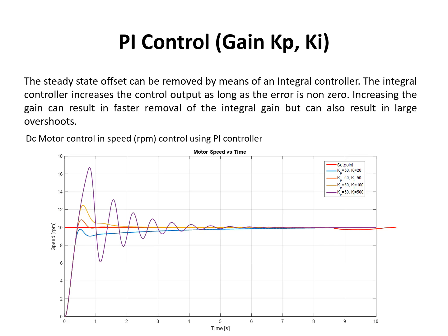So what I simply have here is the same proportional gain, and simply changing the integral term. And what we can see is that the rate at which the error reduces increases the higher the gain of the integral term, up to a point. So again, we have a Ki of 20. We see that it takes a while for it to go down to an error of 0. And as soon as we increase the gain, we see that the error is reduced much faster. But now, as soon as we increase the integral term gain further, we can see more oscillatory nature, a higher overshoot of our system.